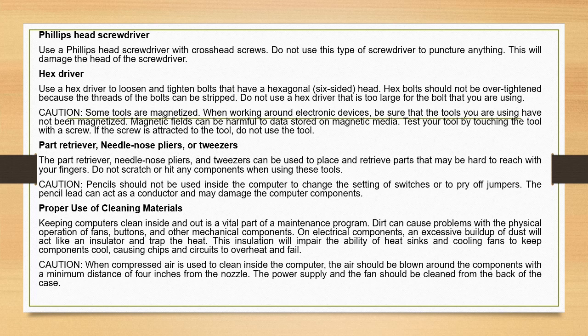Caution, some tools are magnetized. When working around electronic devices, be sure that the tools you are using have not been magnetized. Magnetic fields can be harmful to data stored on magnetic media. Test your tool by touching it with a screw. If the screw is attracted to the tool, do not use the tool.